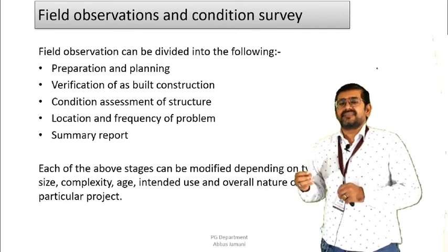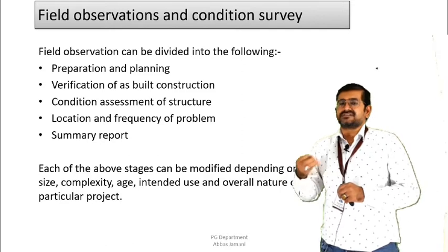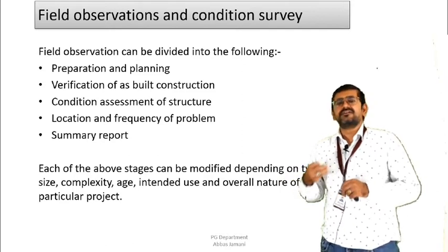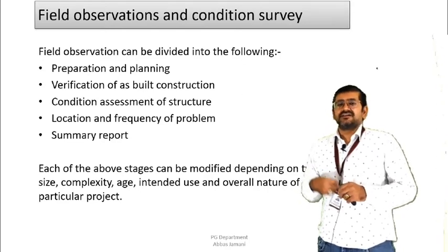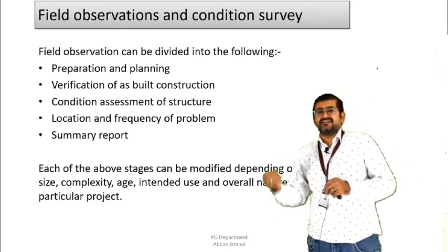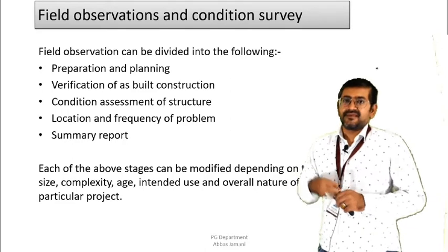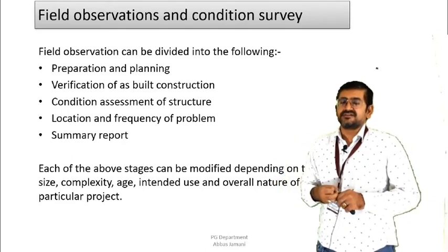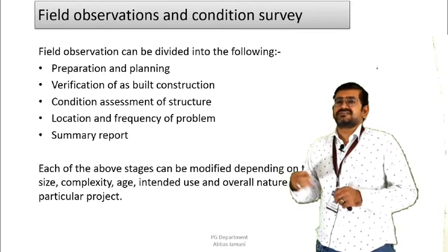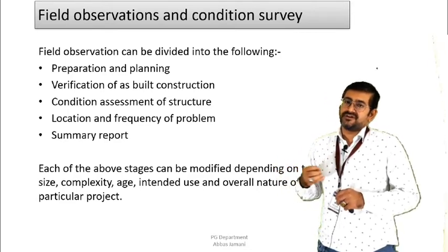Everything will be noted. If cracks are there, what is the width of the crack? What is the depth of the crack? What is the location of the crack? You take some photographs. You make a video wherever necessary. Right? If any uneven loading is observed on the site, then you take a note of that, right? What is the cause of this loading? What is the cause of changes or maintenance that was done over a period of years? These are all different things that you observe on site and you record them into different categories.